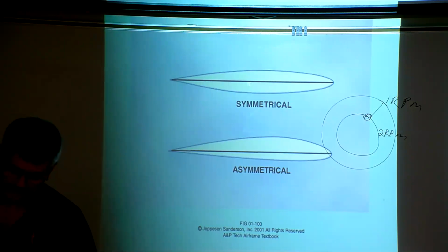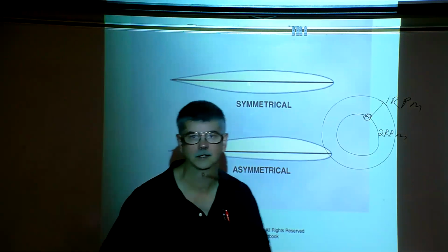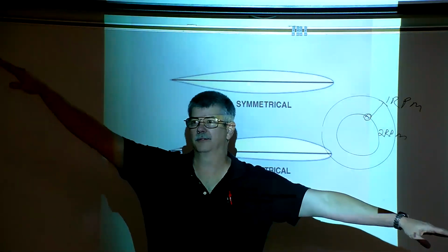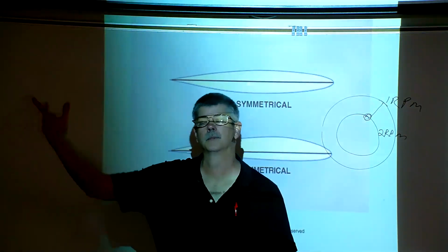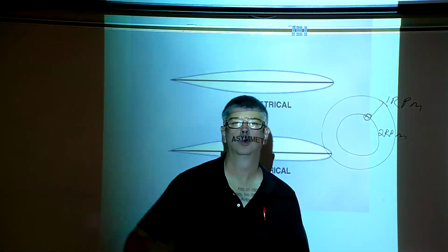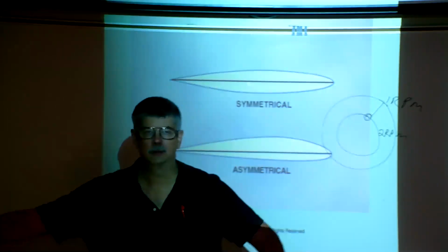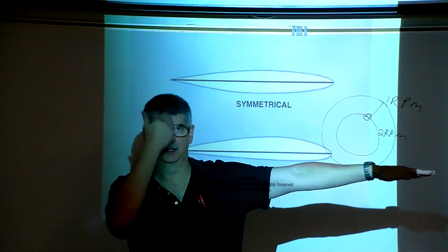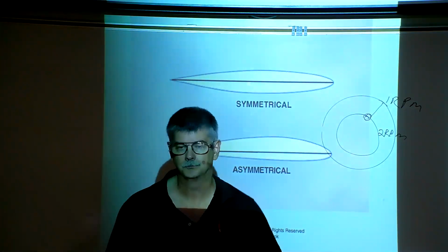We already hit upon it, but the next one is what's known as the Coriolis effect. As I said, as a rotor blade flaps up, it gets closer to the center of rotation, so that blade would want to advance or lead. If a blade is flapping down, the center of mass is getting further away from the center of rotation, and is then said to lag.